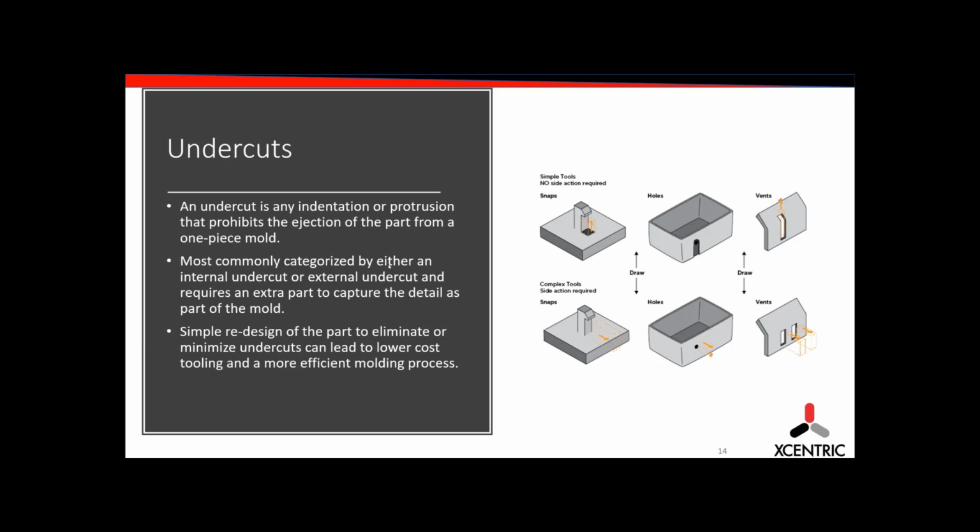The question has come in regarding this slide. In the top image, it appears you're saying that you can make a hole without a slide. Is that so? If so, I don't understand how. I'm assuming talking about this center here. I think so. There are creative ways where you can. It doesn't really show the inside here, but you're just creating a shutoff, and you can create holes with two halves of a tool. You're basically splitting half of the diameter from the inside and half on the outside. And when you put the two together and shut off on that, you do have a void left over.